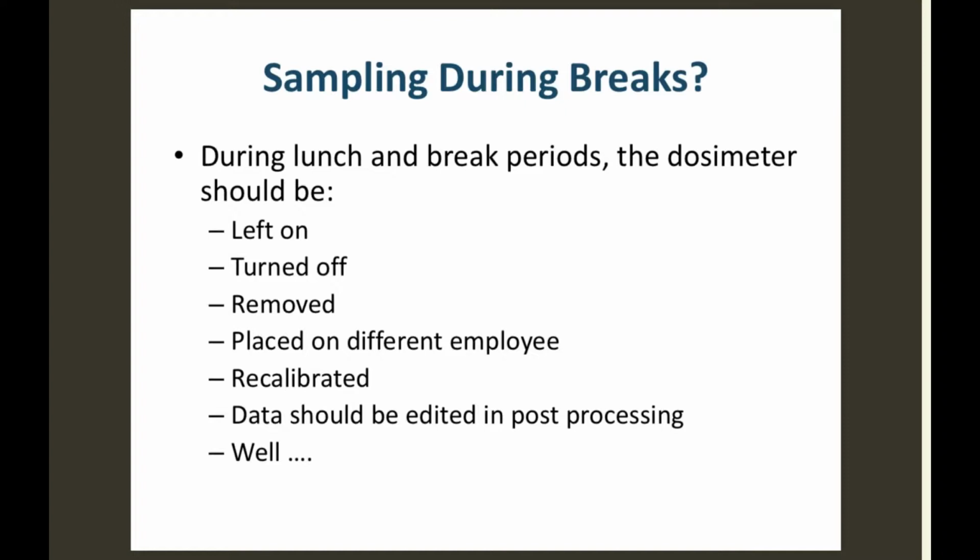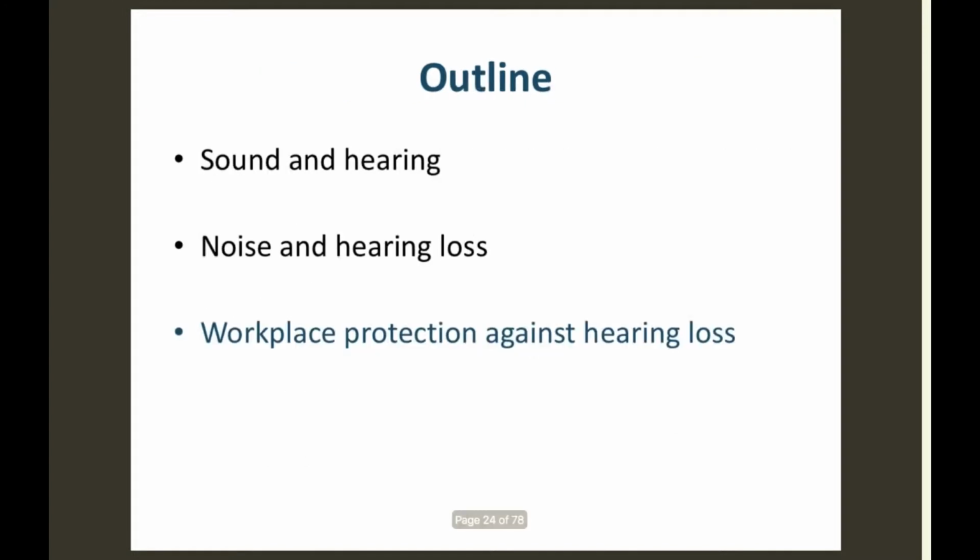For instance, if you do take a break, in other words you take readings in the morning, right? Take a break. What are you going to do? You're going to recalibrate it before and after, in other words, put it back on the guy later. You're going to calibrate it before you do it. But on a practical basis, if it's not a ridiculously noisy environment and it's part of his 8-hour workday, his half-hour lunch break or coffee breaks, I probably would leave it on. Because again, you're interested in what the exposure is over the 8 hours that he's actually working.